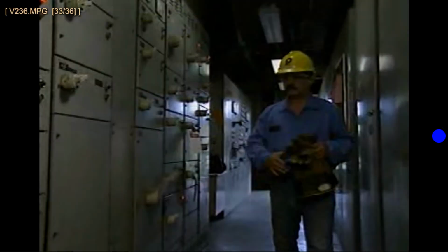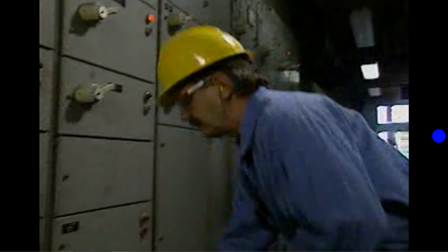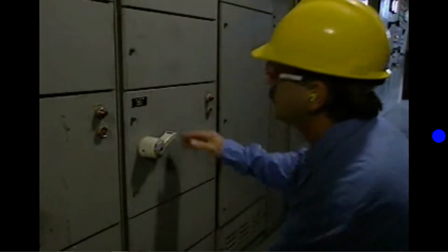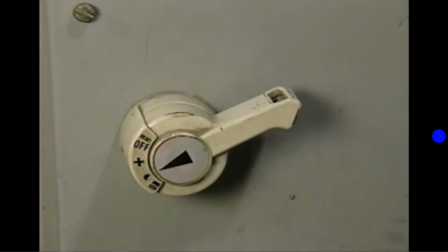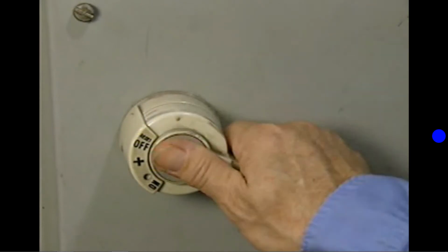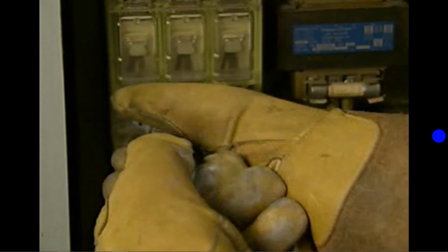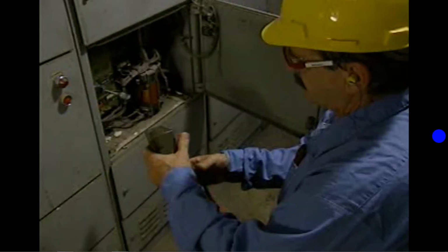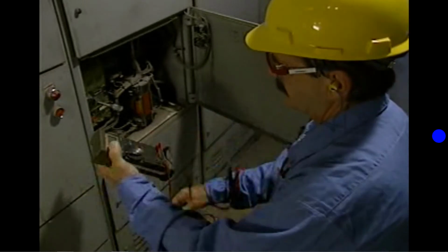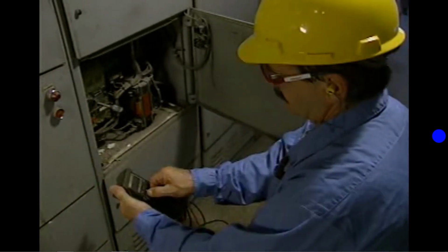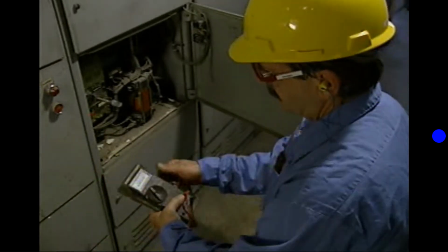To begin troubleshooting, the motor controller should be checked for voltage while it is energized. This controller has a safety feature that prevents its door from being opened while the controller is energized. To get around the safety feature, the circuit breaker is switched to the off position, the controller's door is opened, and the breaker is switched back on again to energize the controller. Once the door is open, a voltage tester or a multimeter set for voltage readings can be used to make sure that there is incoming power.